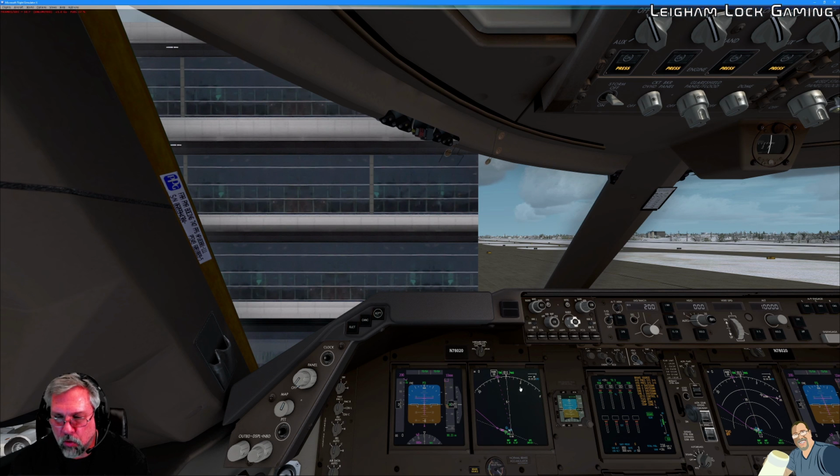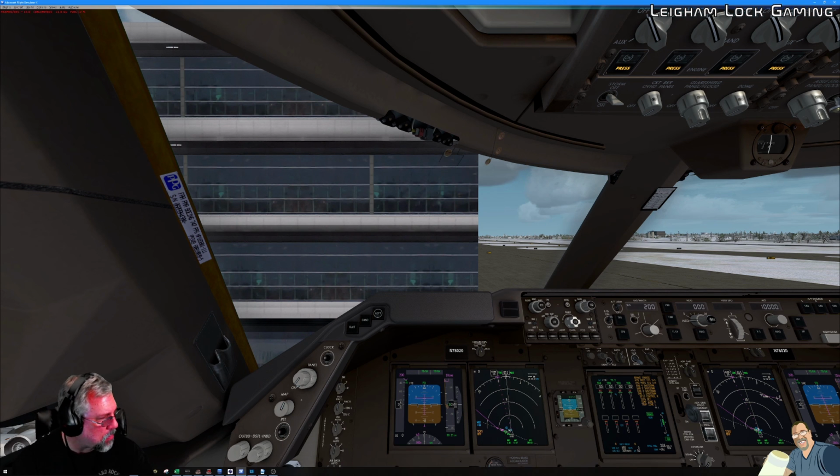We're in map mode. If we want to see the TCAS off, we click the TFC. So here's our TCAS off and our ARC range lines added onto the navigation display. We don't need any of these other settings turned on right now. If we wanted weather, we could certainly click the weather and see if there were any weather conditions. Like I said, the weather's pretty clear right now, so we're not going to see anything on this display.